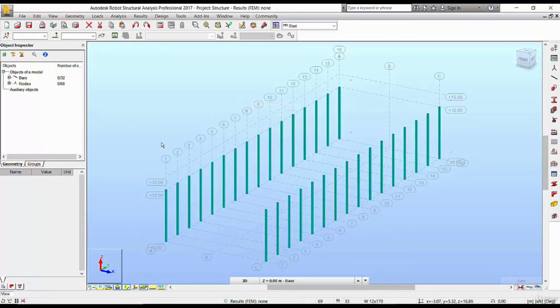Now we want to facilitate our work in the next steps. We must create a group for these columns. So we want to select all these columns. We go directly to this group and press on it to select all these columns directly. Then on the left of our window we go to Groups, and we go to create group out of the selection.